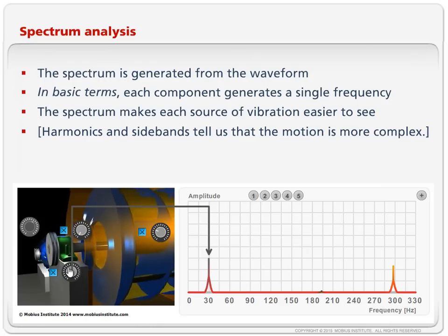It's not so much to do with criticality. Criticality tells us whether we can justify doing it. The PF interval, or the time to failure, tells us how often we should do tests. But anyway, if I take one measurement and then I come back 30 days later and it's like this, 60 days later it's like this, I can say, okay, the unbalance is growing. And I can decide whether I want to do something about this high level of vibration.